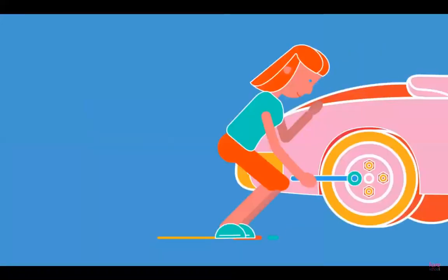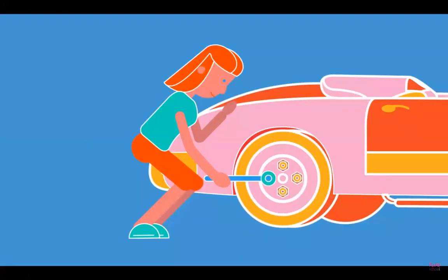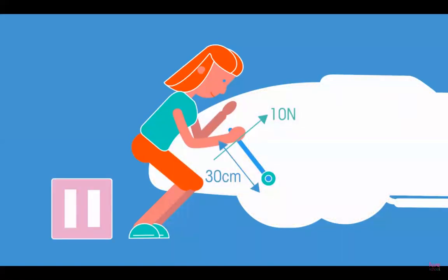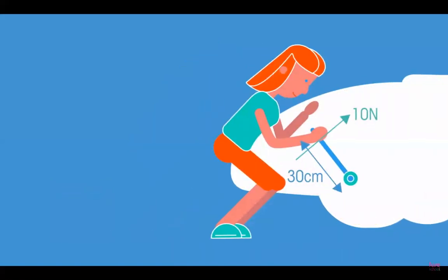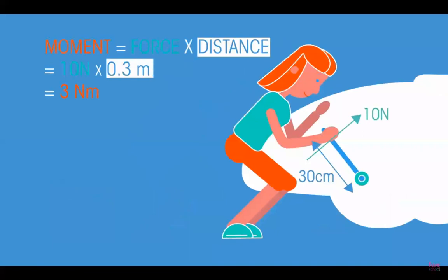Here's another example. Can you work out what moment the woman is applying to tighten the wheel nut? Pause the video and work it out. Did you get 3 newton meters? Were you careful to change the 30 centimeters into meters?